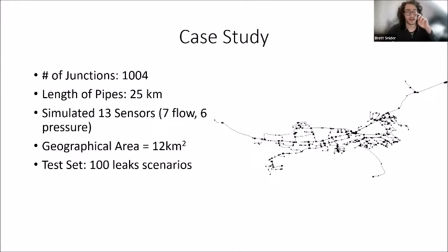Again, this is a skeletonized graph, and this is typically the case for water systems. So not every single service connection, et cetera, is on there. But this is why it's important, because although the leak could occur anywhere throughout it, the search area would encompass it even if we simulated it at a specific node.